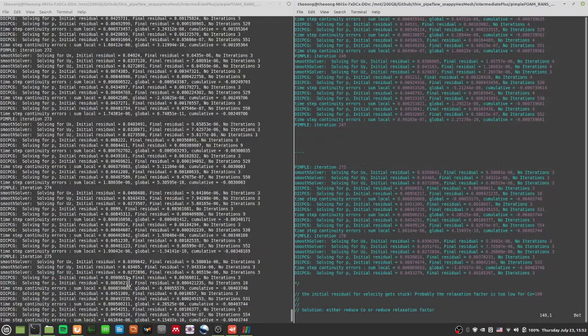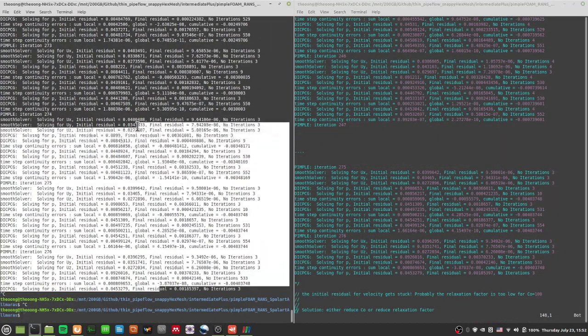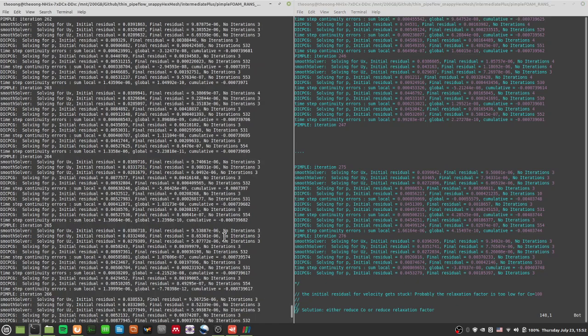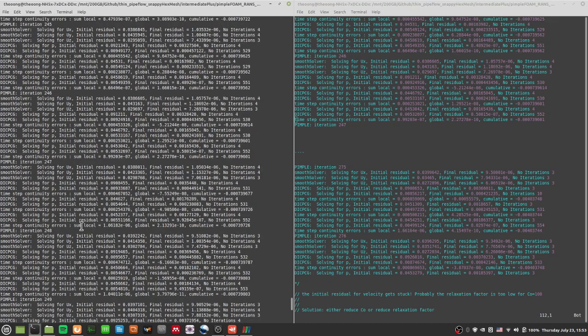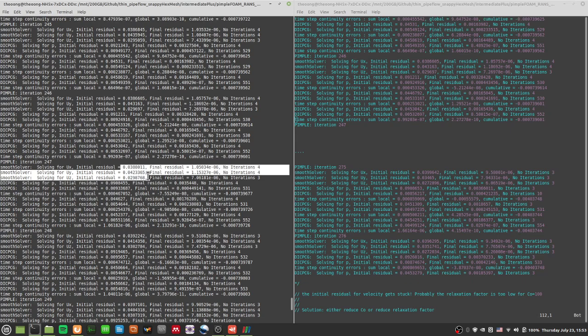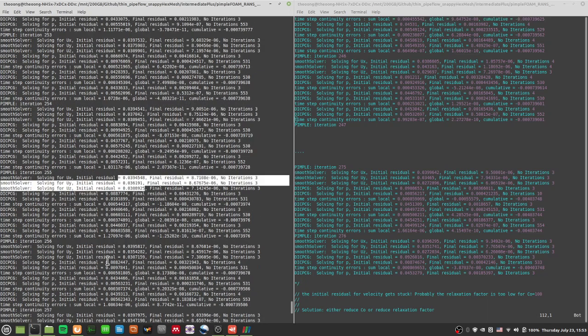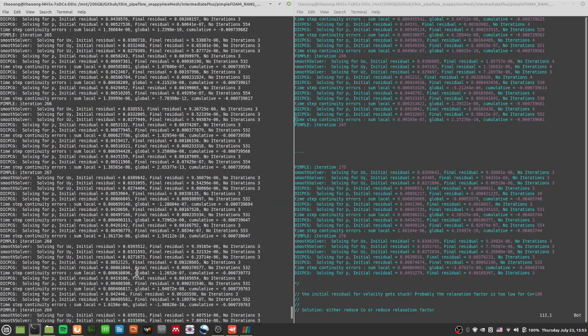Hello everyone, welcome back. In the last video we tried to accelerate the solving of this SpalartAllmaras pimpleFoam case. This was the result. You see that the pimple iterations go into the 200 plus, so there's something that's not converging. If you take a look at the initial residuals, they will hover around 0.2 to 0.4. If not, they'll go down and then go up, and go down and go up.